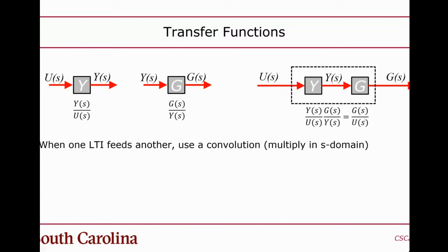So it works out algebraically, and if you multiply the S domain fractions of polynomials, it also works out. You can scale this up as big as you want. In fact, what we were doing before was taking the Dirac, the unit impulse, which is just a 1, and multiplying it against the transfer function that we synthesized. But in this case, you could take an arbitrary other transfer function and do the multiply. This is how you can build up larger systems.